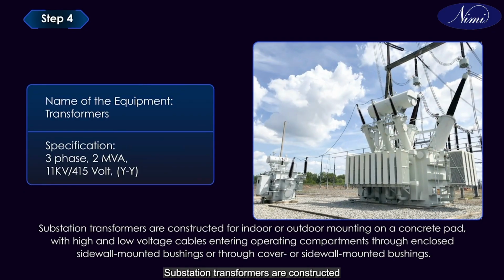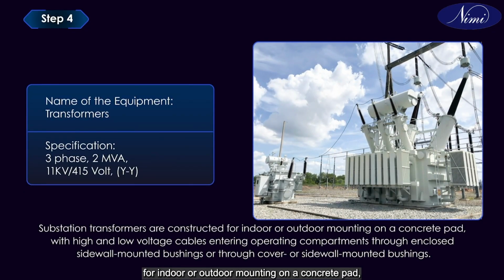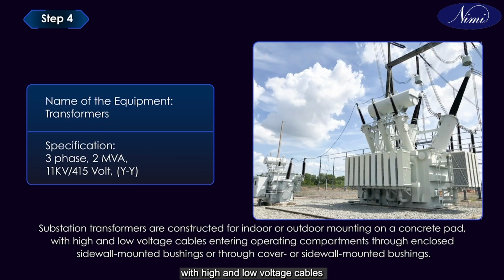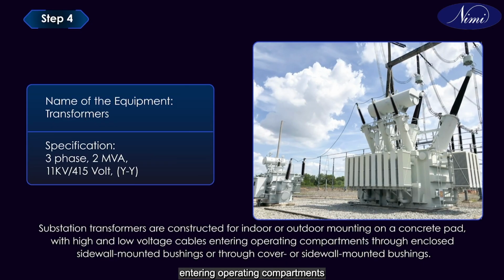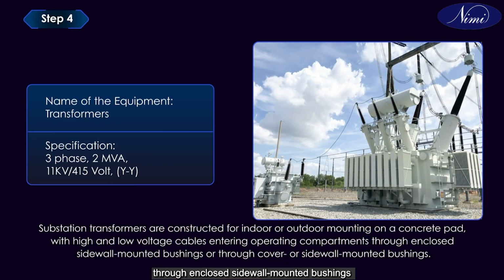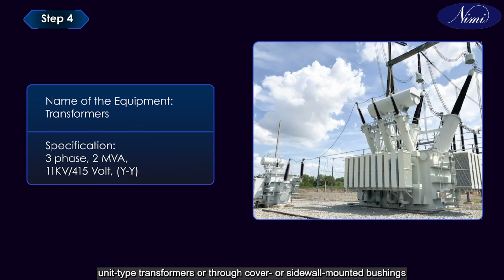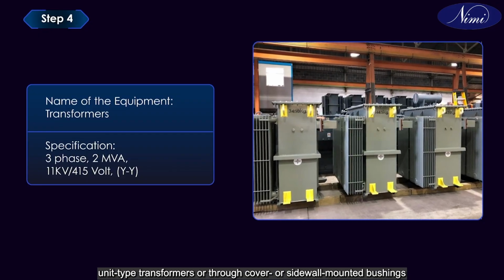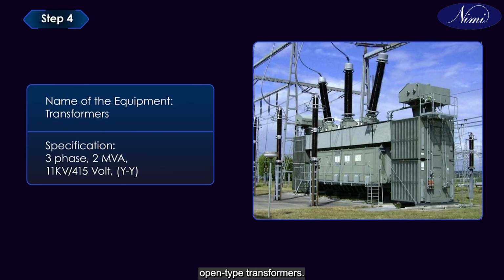Substation transformers are constructed for indoor or outdoor mounting on a concrete pad, with high and low voltage cables entering operating compartments through enclosed sidewall mounted bushings, unit type transformers, or through cover or sidewall mounted bushings, open type transformers.